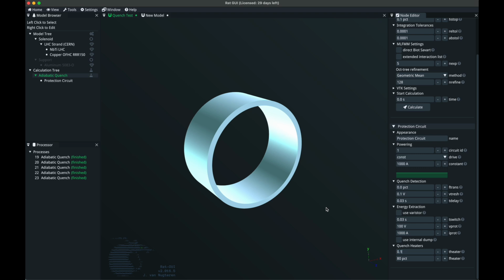And so for LTS, we can sort of say that at, I guess, 100 milliseconds, 80% of this coil will probably be quenched. So then it's also important to make sure that the protection voltage is set to 0, because otherwise it will assume that there's still a dump resistor or something like that in place. So if we set this to 0, we still have a switching time of when your power supply switches off. In case you have an external resistor, it switches from the power supply to the resistor. So it's a switch that switches the resistor in series, but also turns off the power supply.